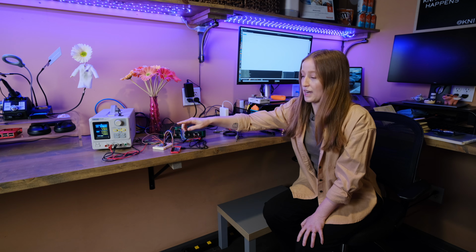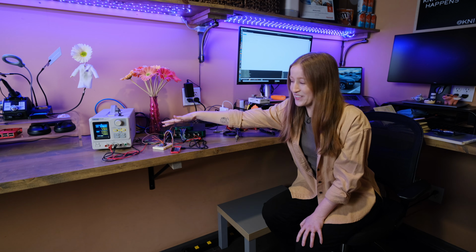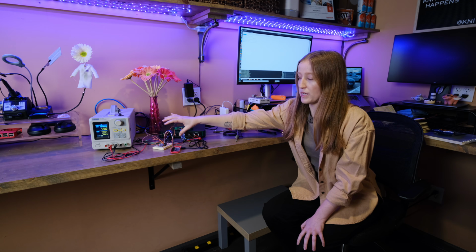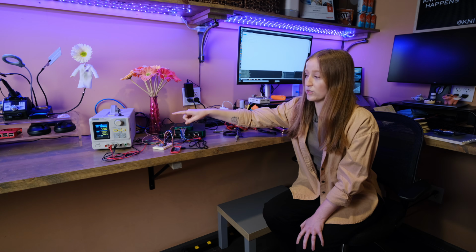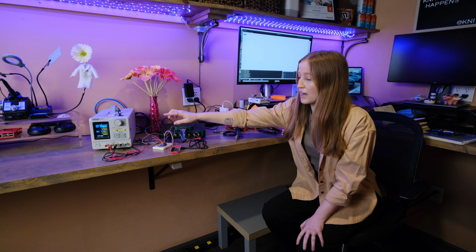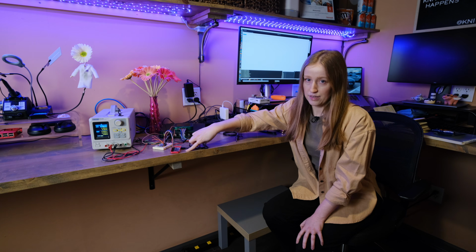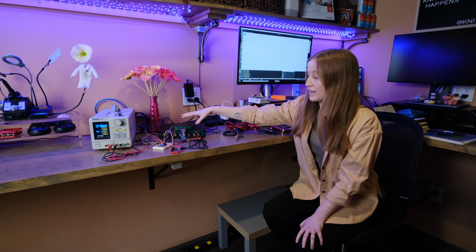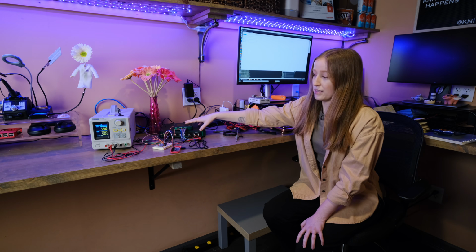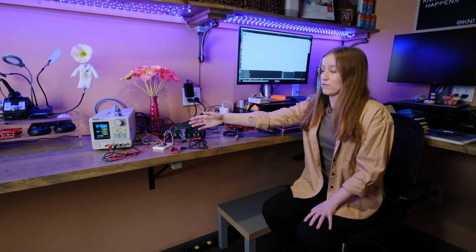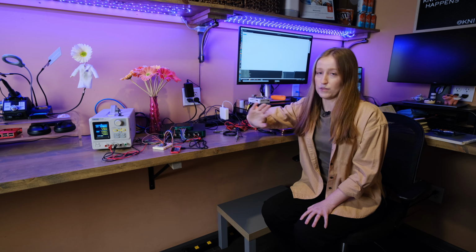Otherwise, I would just have these leads connected straight to it if I weren't trying to have these in the middle. And as well, it gives me multiple ground points, because I have to have a common ground between power supply, target device, controller device, aka the Raspberry Pi Zero, and then my 2 USB controlled instruments. So that allowed me to pull out to a ground rail on a breadboard and have as many connections as I need.